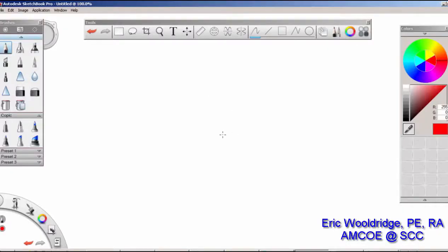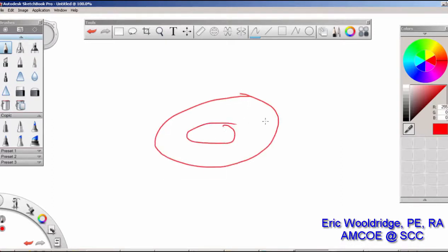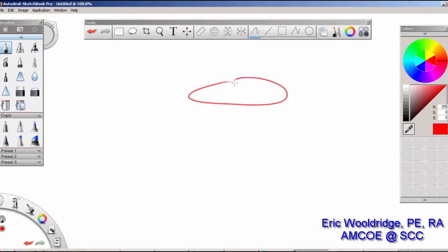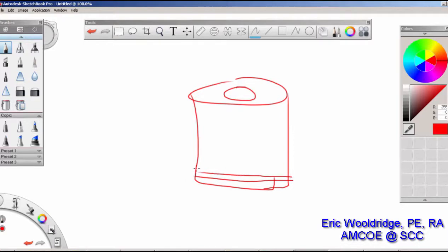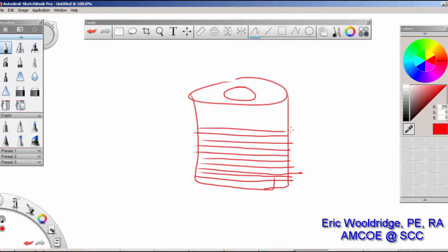The reason we call it slicing is because the slicing program is writing code for every layer. So layer 1 has its own set of codes. Layer 2 on top of it has another set of codes. So what the slicing program is actually doing is taking your 3D model and virtually slicing it and writing a code for each slice. That's why when we say slicing, that's literally what theoretically is happening. It looks at your CAD object per sliced layer and writes the code for each one, and then just says execute all these slices.